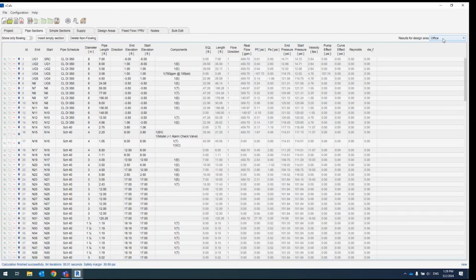And obviously when you switch the mapping, that now means these sections are using the C factor and the internal diameters for the appropriate size pipe for each of those pipe sections for the new pipe schedule.